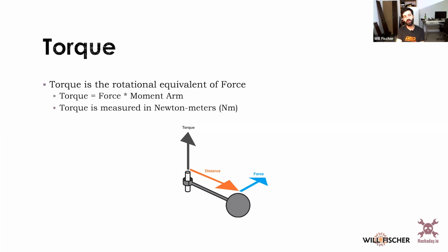Torque is the same exact principle, but taken into a rotational frame. We as mechanical engineers oftentimes find things spinning around, so it's helpful to multiply that by the radius it is away. That happens for angular velocity as well, and it turns out that the radius component drops away. But if it doesn't, and you have different forces acting at different radiuses away from a thing, then that's a really important thing to calculate in the way that you rotate something. So a torque very close to the shaft can be counteracted by a relatively minor force far away from the shaft of large torque.